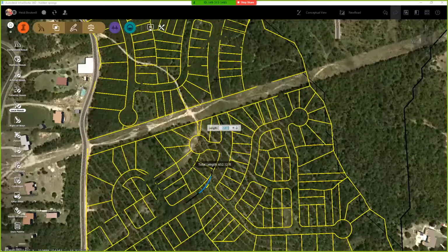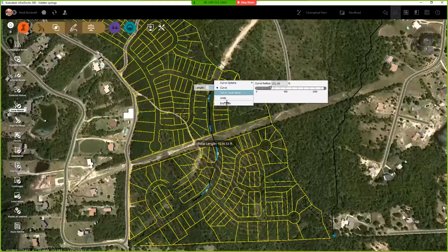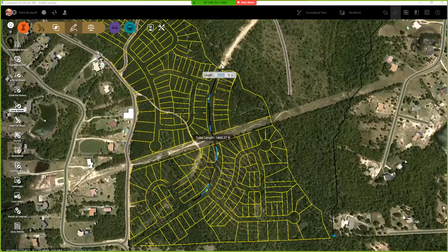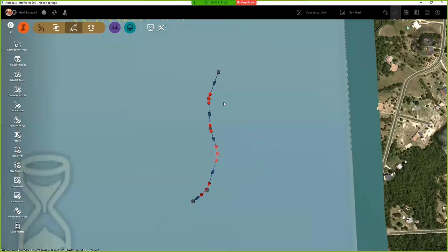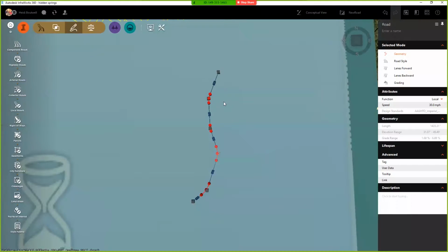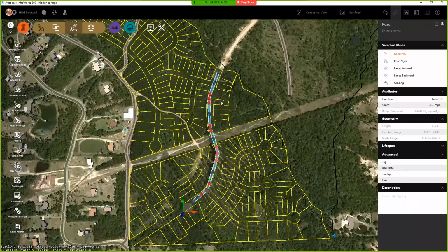And you notice I have a tooltip. If I right click, I can put in curves, spirals. I can undo and end draw. I'm going to go here, right click, and I could double click or hit end draw. Your choice. Very fast. Can't do that with alignments and profiles. Wish I could. Remember, this is preliminary. We're just showing the client really what we would like to do.